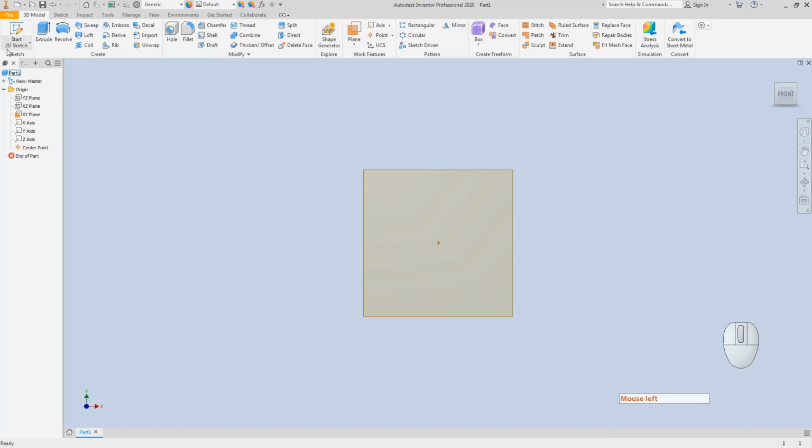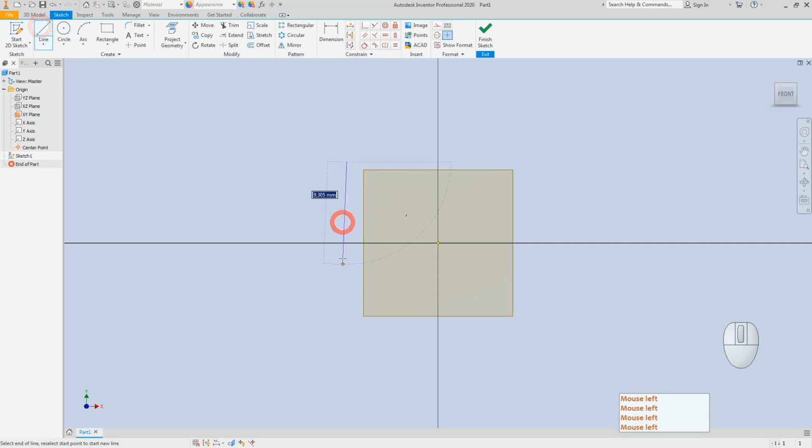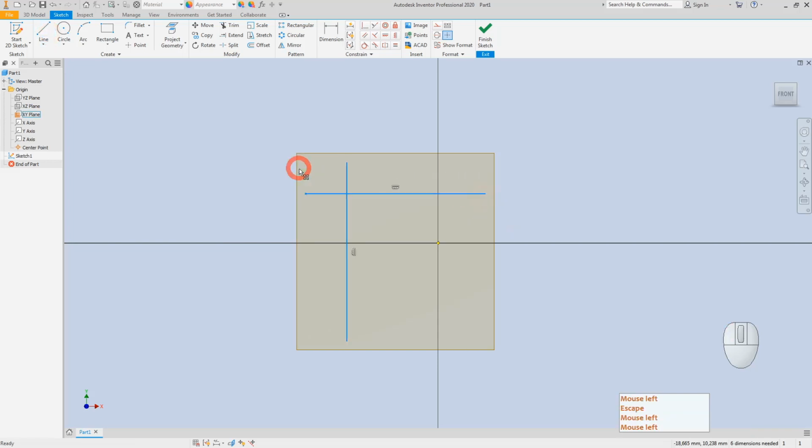Let's start modeling. The first thing that I'm going to create is the axis lines around the origin point. For this purpose, I'm going to create 2 arbitrary lines and attach them to the origin point by the coincident constraint.